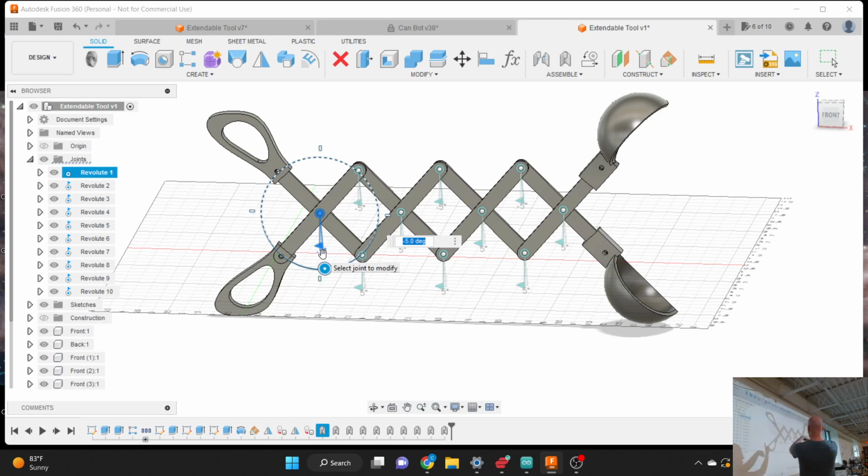If the flags were pointed in opposite directions, it could be that even though your gears are moving against each other, they're both moving in the negative direction or both in the positive direction because those flags are pointed in different directions. So this is just a good practice here. In reality, one joint is driving all of these joints because they're all connected. But we don't want to create something that's going to grind and get destroyed as soon as we make it.